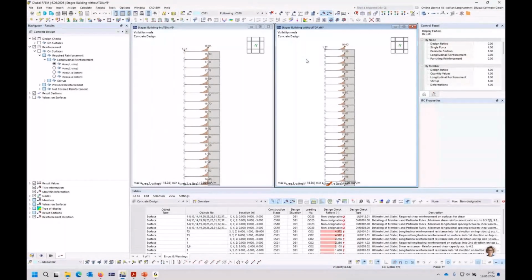There are structures, depending on how complex or how high they are and how long the construction process is, where you have an influence due to long-term behavior due to creeping, where there could be a redistribution of the internal forces. Like shown for the first example, there was a quite significant change. Of course, it was due to the added support in the middle.